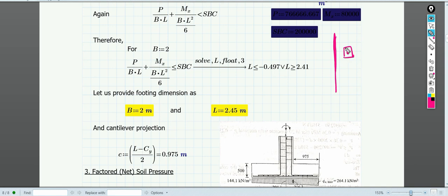In that case, you might not have the liberty to extend the footing, as there is a boundary issue. You might have to limit the width or length. That's how exactly you have to find out. This is from your engineering judgment.